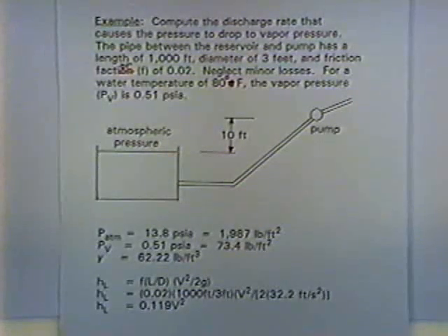And it can be a real problem because then the vapor bubbles go into the pump, and then actually most of the damage is done when they turn back to water and sort of implode, not explode, but implode, and they can damage the pump and they block the flow and so forth. And so there's a physical limit of zero pressure, but there's also a practical limit of vapor pressure when the liquid water starts getting vapor bubbles in it.